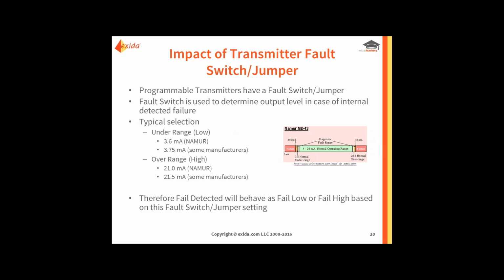that demonstrated the ranges. So basically, what this standard says is that 4 to 20 milliamp is the normal operating range. Between 3.8 and 4, and between 20 and 20.8 are what they call the normal over ranges and under ranges. So that's where your signal may end up a little bit here and there.